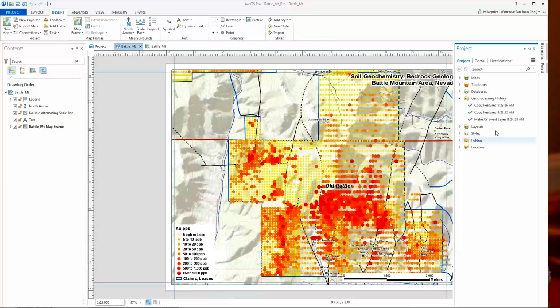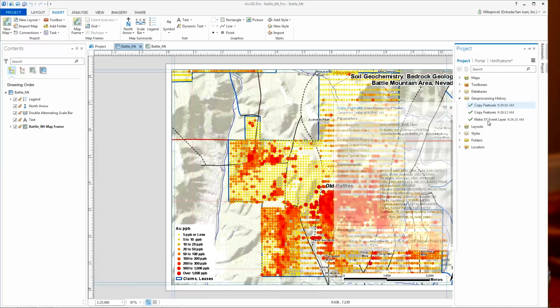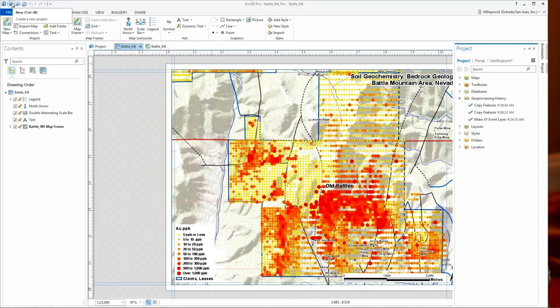and be sure that it tracked all of these task parameters. So my bet is that yes, it does. It definitely records it in your project. So be sure and save your project often to lock these in. In fact, my typical geoprocessing workflow is run the process, check the process, and then save the map. In case something goes horribly wrong, I can kill the map without saving the process and then start again. But yeah, we'll keep an eye on that.